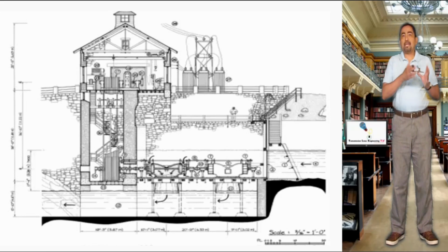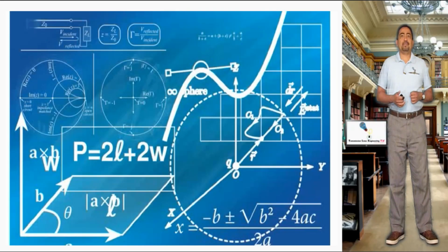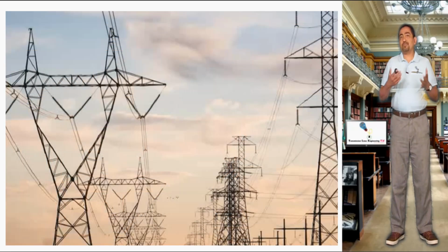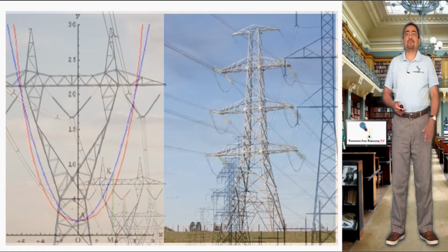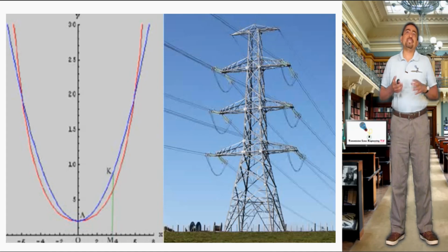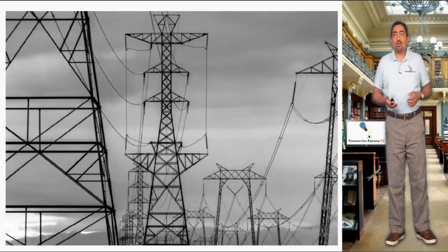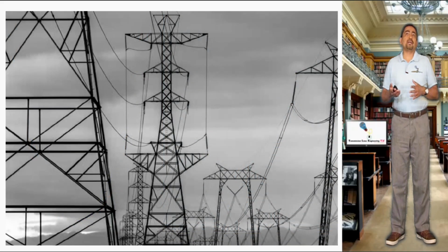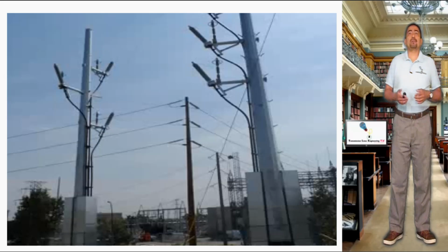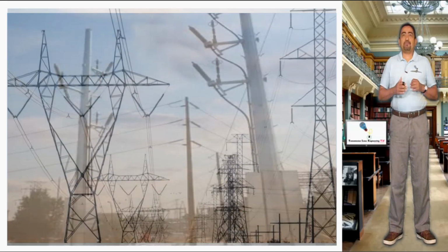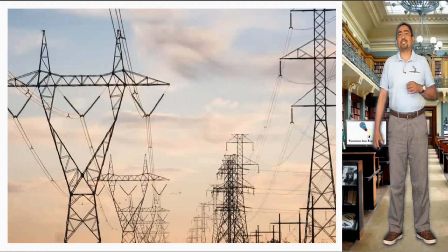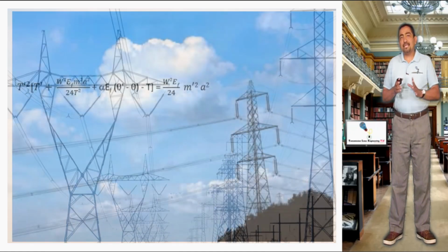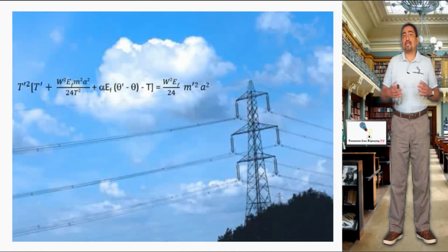How the theory was developed to design a transmission line, and as we know, a transmission line requires many calculations that go from the mechanical calculations of the cable to the design of very specialized structures, such as, for example, a phase transposition tower, or maybe a tower for an underground-overhead transition. However, regardless of the complexity of the project, the basic components for the design of a transmission line are as follows. First, we have the mechanical calculation of the cables, or calculation of the catenary.